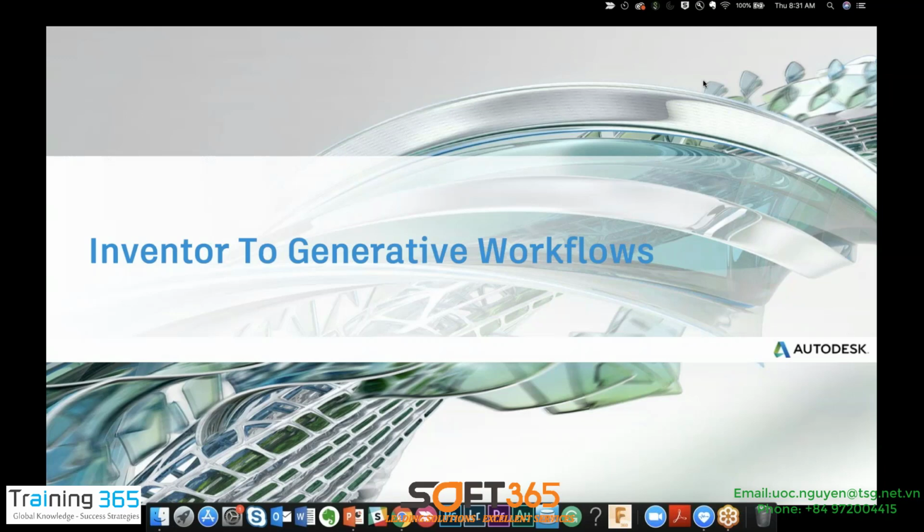And then the last piece, just want to make sure everyone's comfortable understanding some of the decisions we made around this functionality being part of the collection as opposed to core Inventor. So obviously today in Inventor proper, there's a lot of features and workflows that allow our customers to do tolerance-related items. So we have the model-based parameters where you can apply some basic tolerancing and run the high side and the low side through the parameters window and check for interference on parts on various manufacturing deviations and or maximum or minimum sizes. So that's one option that's in core Inventor today.